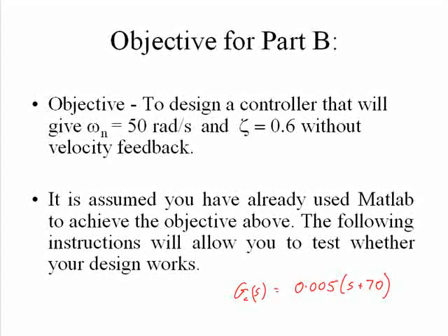For this video I'm using a proportional plus derivative controller with a gain of 0.005 and a zero position, an alpha value of 70.